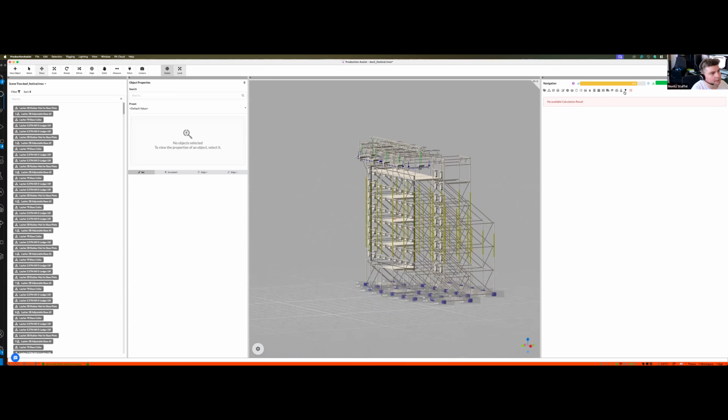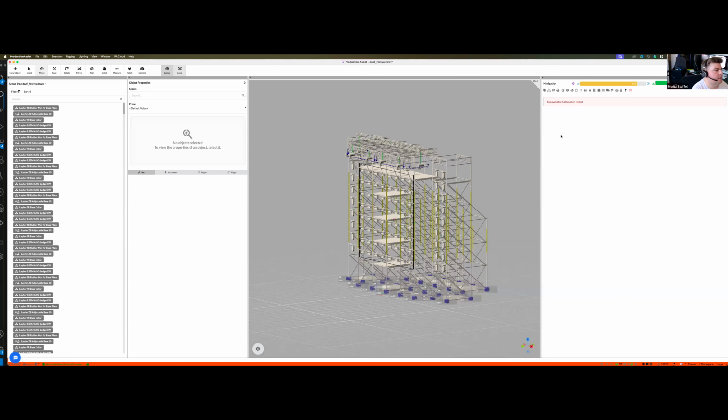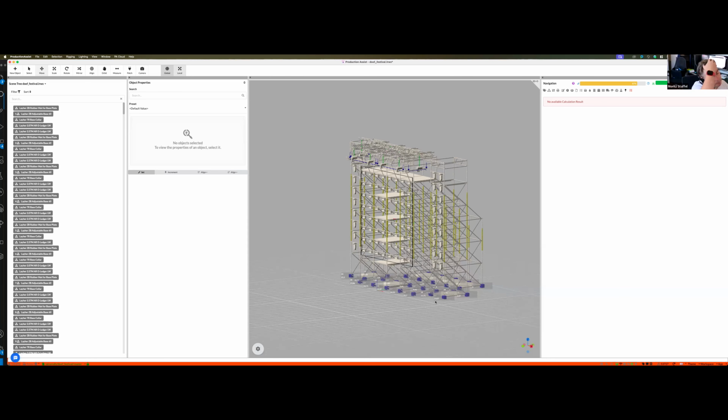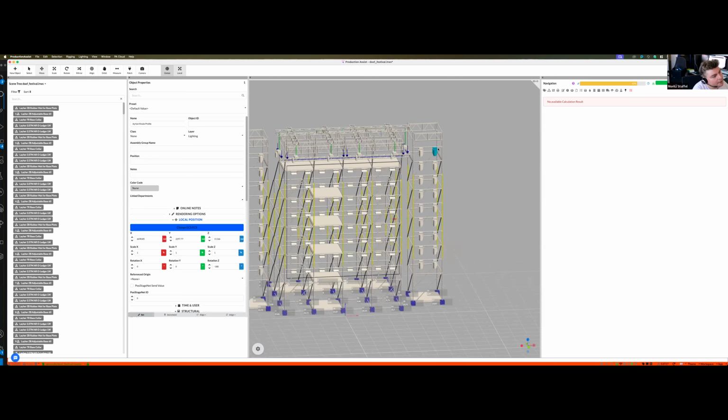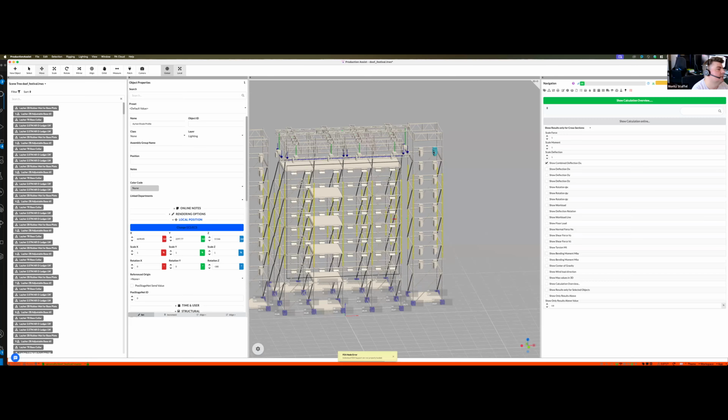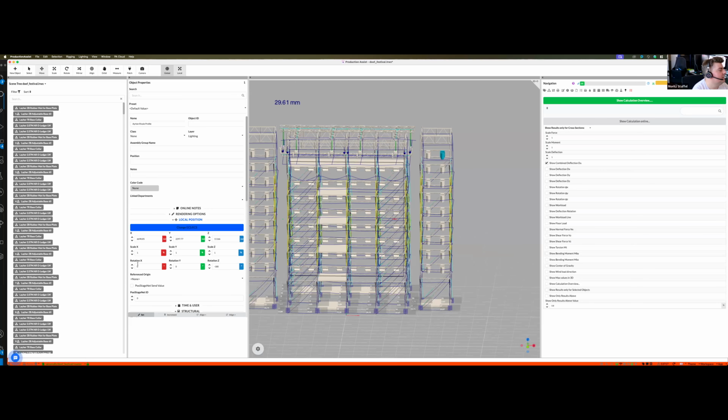This is a layer structure that we have in here. It's a normal layer structure, but it's using fixtures that are standing in here. So for the sides, the fixture is a wind load plane. With this kind of wind load plane, we actually needed before to calculate the area of the fixture which is inside the wind, and we needed to place a point load in here. It was quite a lot of work to do this, so it was always kind of the unlucky job.